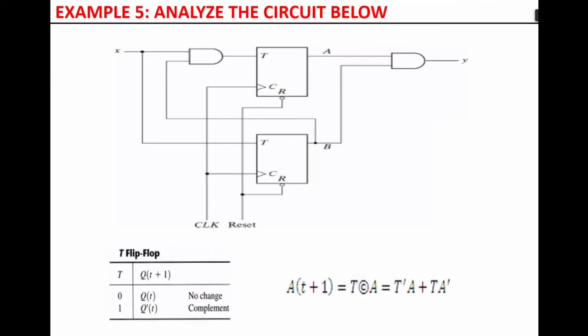I'm sorry, for this, Sahil, for this case, forget about the clock and reset. And it's a Moore circuit, you are right. It's only affected by the state, the input does not go directly to the output. Thanks, Tokozani. So we've got that.